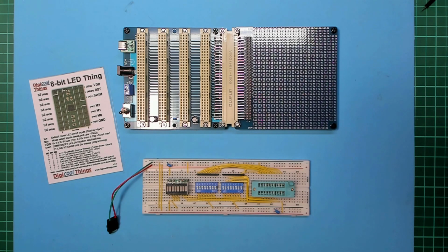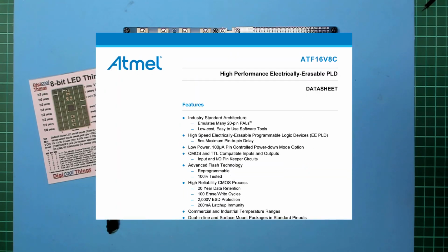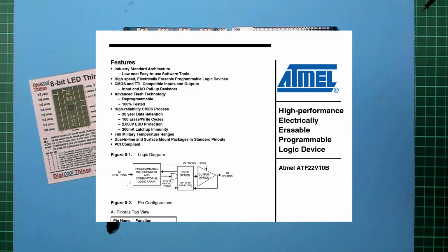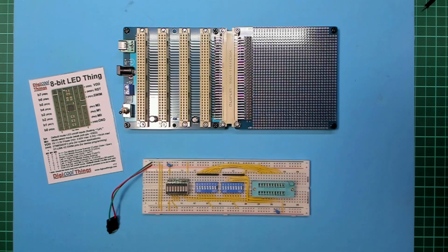The logical conclusion is to utilize a retro PLD device, which, fortunately, Microchip or Atmel still produce as the ATF16V8 and ATF22V10, etc. Some folk may disagree with this approach, but I believe this is a logical solution for creating a flexible but still retro address decoding design.